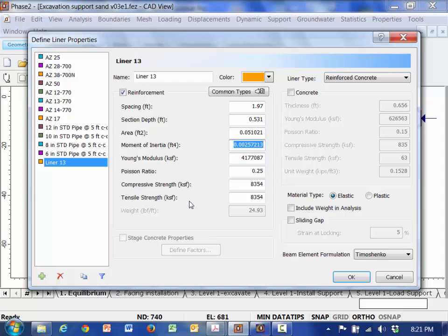And it's going to back calculate the equivalent beam for you. So if you're putting in an H section or a pipe section for a strut, or doing H piles, you can't just stick in the properties for an H pile, because then you're saying I have this continuous H pile that runs the whole length of the thing.